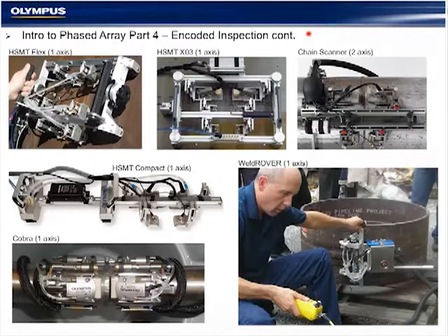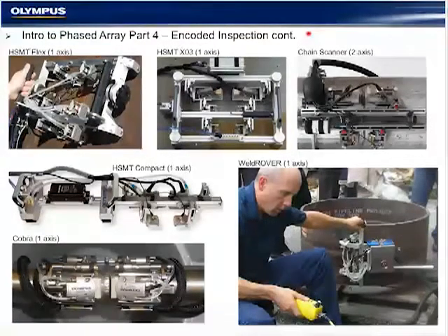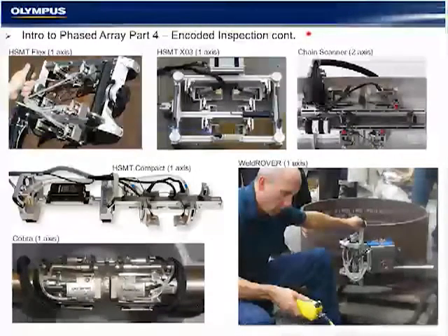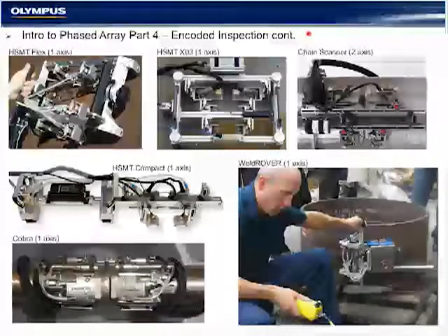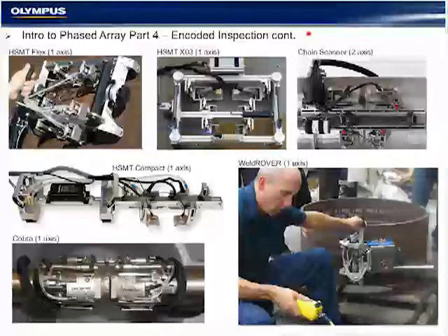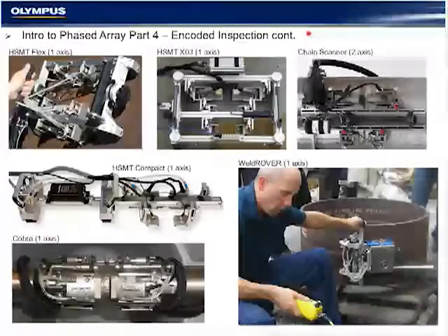What seems like an easy engineering task is actually very complicated. The best scanners are ones that are designed for one particular application. And the more a scanner is adapted to accommodate multiple configurations to include TOFD, phased array, multi-probe, top and phased array, and different one-sided, two-sided access, automated, manual, the more versatile the scanner is, the more complicated it becomes. And again, the best of the scanners are designed and set up for a single axis or one component.